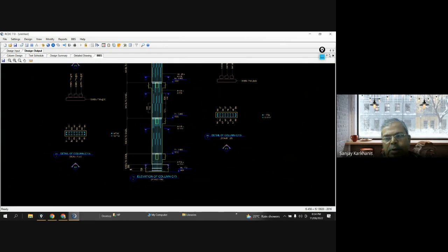Let me show you how it is practically carried out. See, if this is your slab level, this is your slab level. So at L by 4 from both ends, you are not having a lap, and some bars are considered like this.